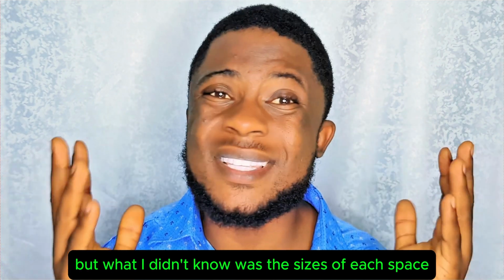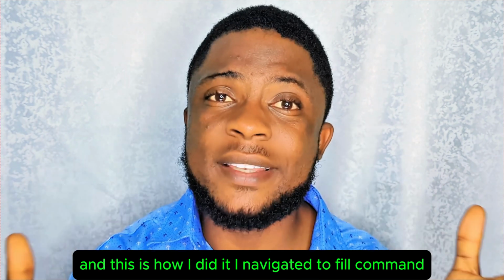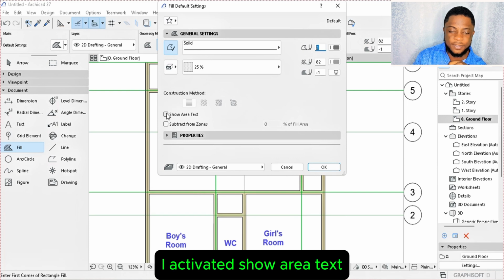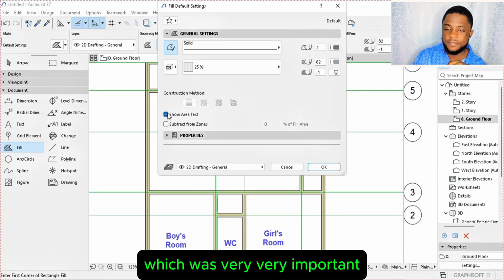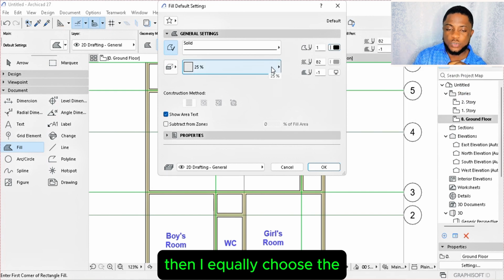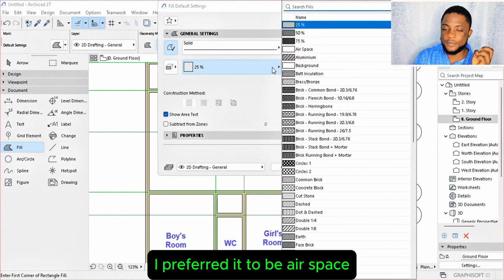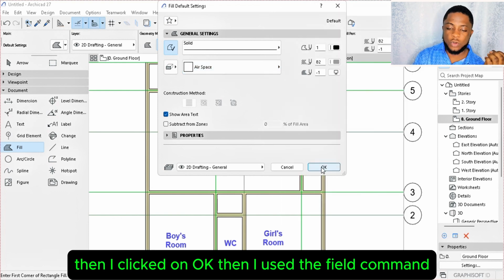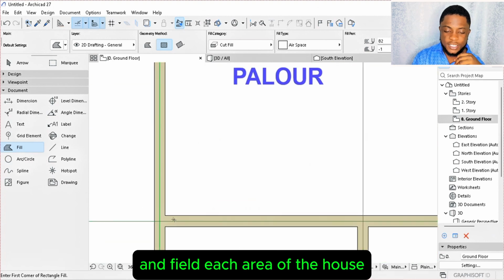But what I didn't know was the sizes of each space, and this is how I did it. I navigated to fill command. Under the construction method, I activated show area text, which was very important, and I wanted the lettering to be black. Then I equally chose how I'm going to fill the room. I preferred it to be airspace, so I didn't want to see anything filled inside the room. Then I clicked on OK. Then I used the fill command and filled each area of the house.